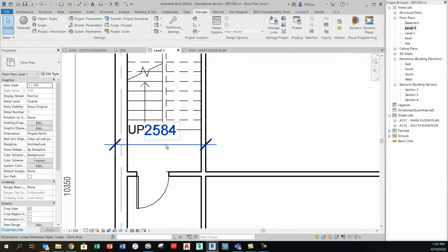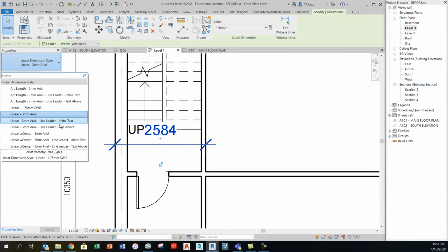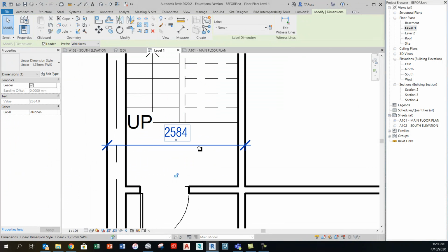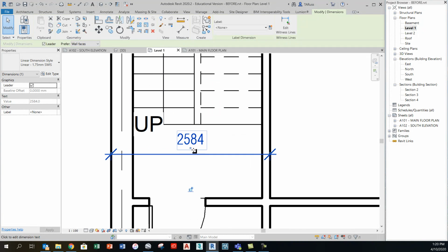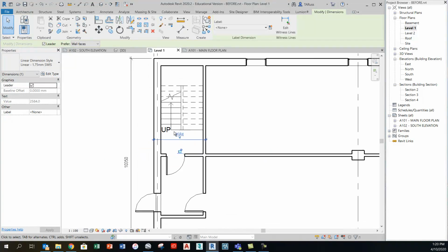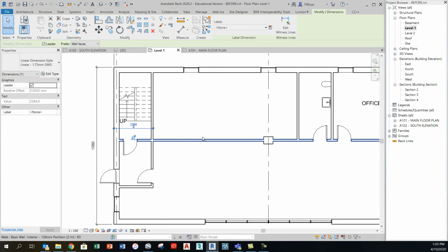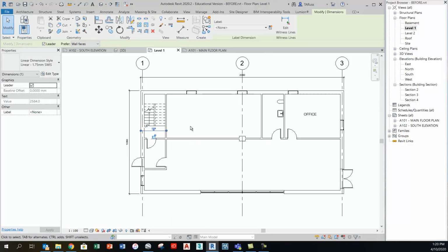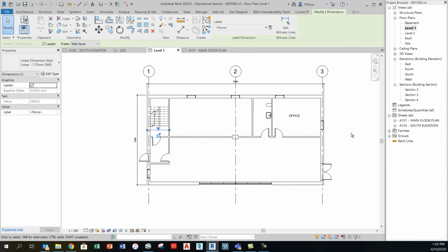And maybe just here, I'll quickly show you that point about using the transparent background instead of the opaque. Whenever these dimension elements or any other text elements overlap with lines, you want to see that line behind. Now, it's not that you want to leave it there. You'd want to kind of bring it back down here and leave it in a spot where it wasn't overlapping, but we don't want to see that kind of blocked out white mask, as I said, which can kind of clutter up your drawing a little bit unnecessarily. Okay, so that's the first and kind of major item on our floor plan.